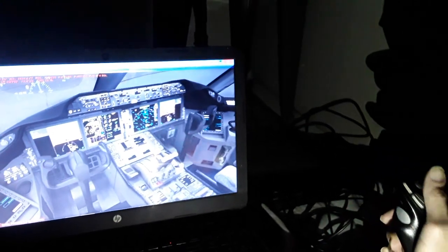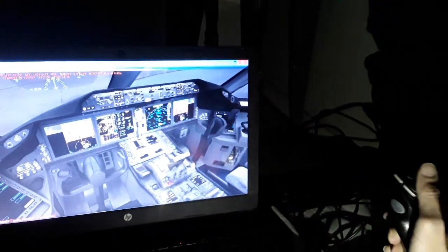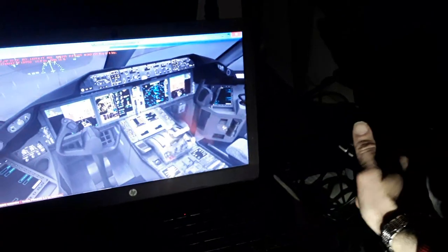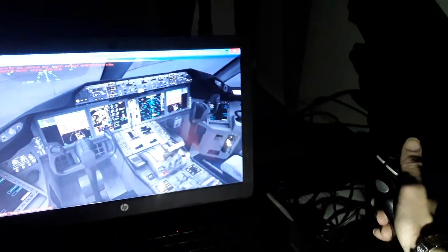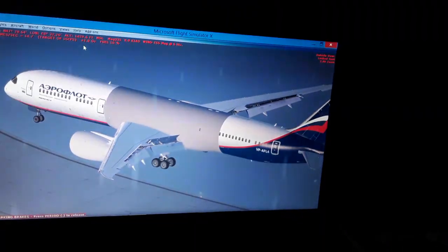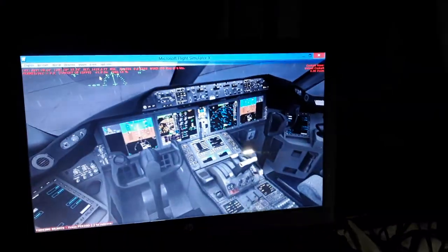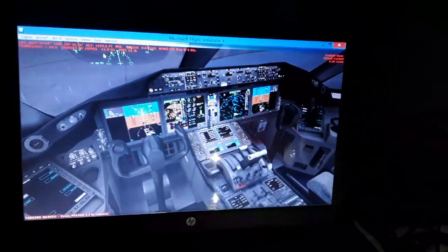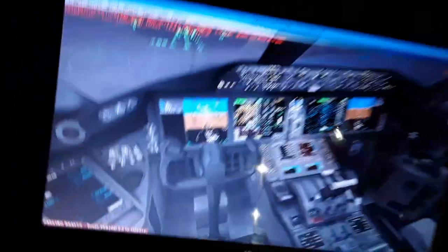You can see the control, the yoke. I have the control column for climb and descent to move the elevator of the horizontal tail, bank rolls right and bank rolls left, turning left and right. Also I use the rudder pedals if I want, only for turning using the rudder, the vertical stabilizer. So we have the horizontal stabilizer over here, moving the elevator up and down. We have also the horizontal trim over here. I forgot to mention, we're gonna trim using the center of gravity in the mean aerodynamic chord position of the aircraft during the whole flight from takeoff, climb, cruise, descent, approach, and landing.